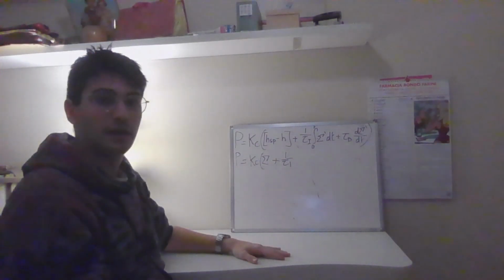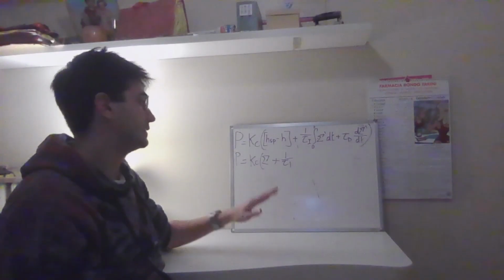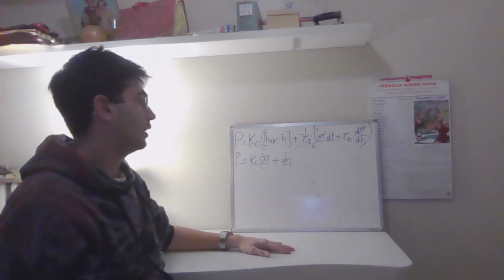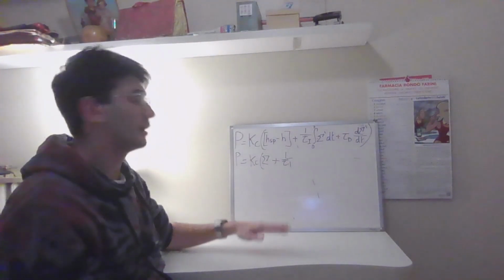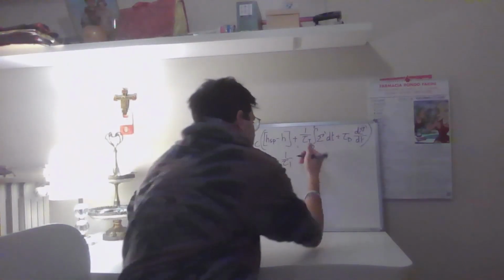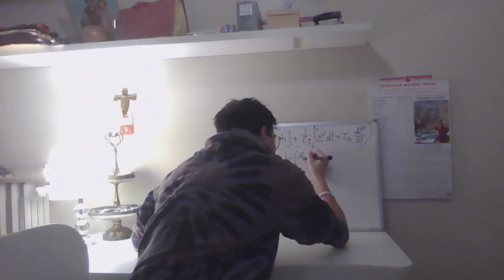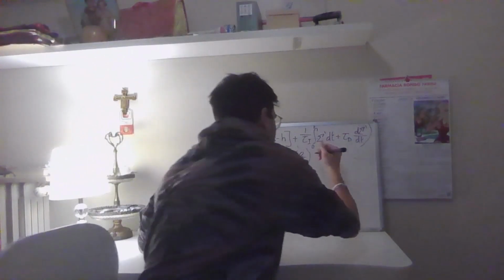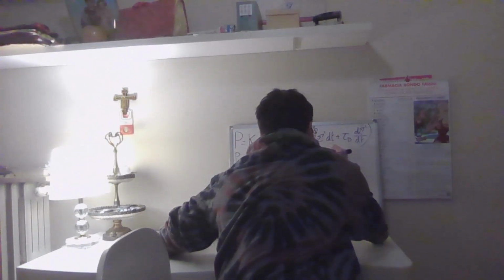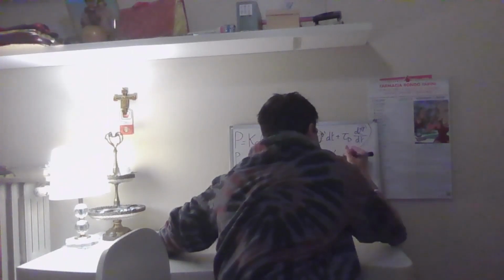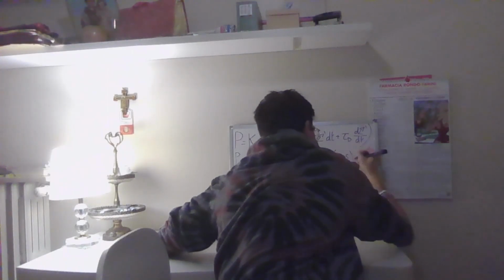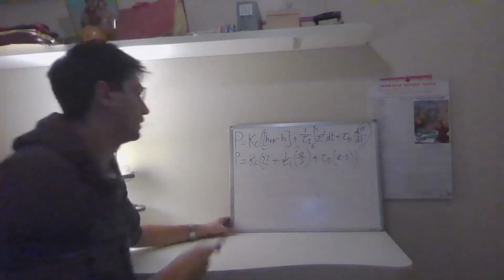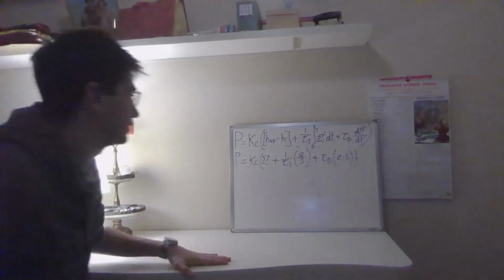And what this is, thanks to the Laplace transform, we know that this is simply going to be equal to the error E over our time dependent variable S. So this will be times E over S, right? And then for tau D times that, this is simply going to be plus tau D multiplied by E times S, right? And this is our new expression. Of course, this E is simply the error that we are trying to determine.